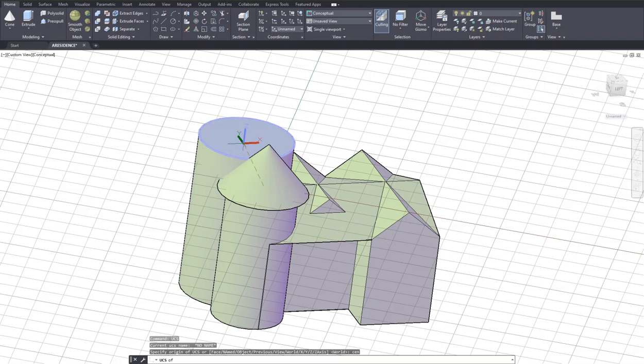current object snaps. So running mode object snaps can be set from the menu button at the bottom, object snap button, and I can show you where it is right now. But a stronger object snap would be typing the name of the object snap at the time you need it. So when I type CEN, computer knows that I'm looking for center of the edge of the circle, of the cylinder, which is a circle. Click on it, okay?